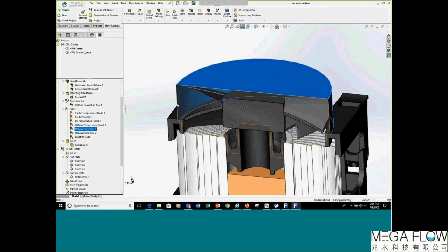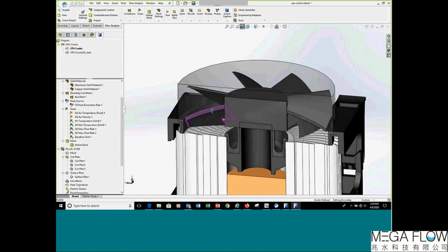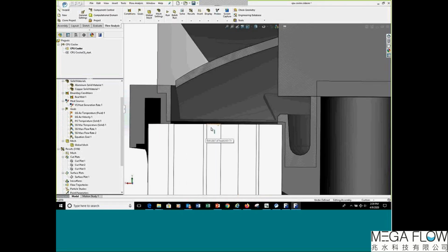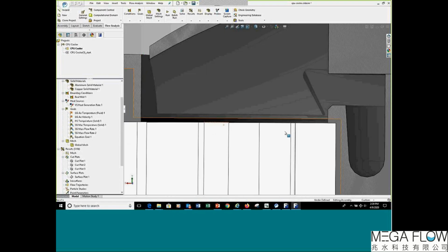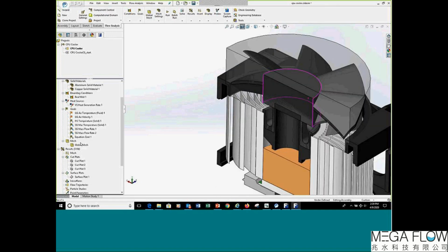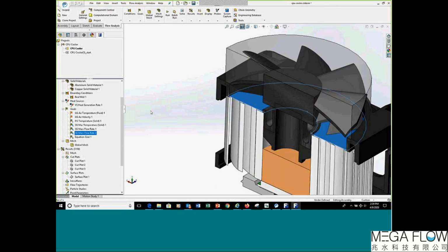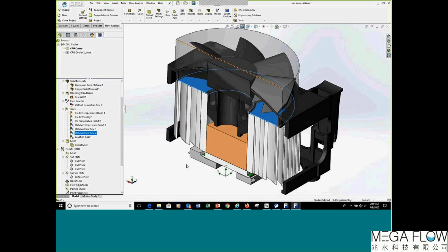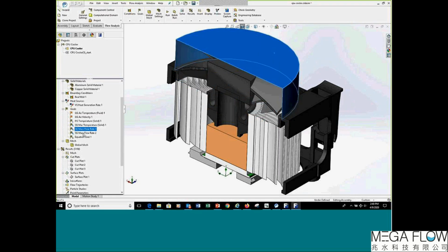On the other side of that, the bottom face of the region is locked between the outer surface and the inner hub surface, the attachment, which means there's an annulus there, and that annulus can be another surface goal for mass flow rate exiting the fan. So all of the flow that exits the fan has to go through that surface.